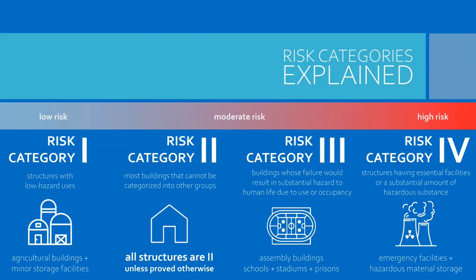In general, most people would consider a small to medium-sized freestanding sign as risk category 1, though the local codes department might disagree. Large freestanding signs or medium-sized ones located near crowded areas should most likely be risk category 2. Any sign attached to a building is risk category 2 unless the building itself would be considered 3 or 4. So basically risk category 3 and risk category 4, those are critical facilities that need extra design for protection.